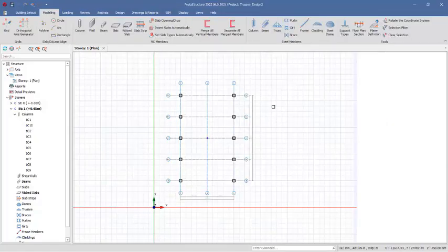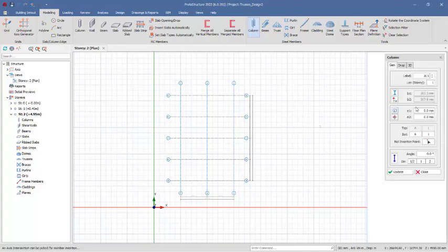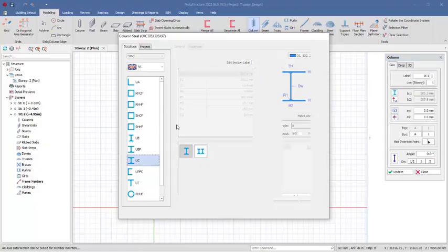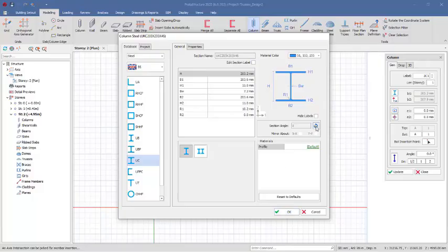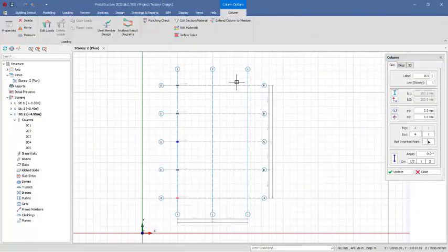Alright, after which we can now navigate to story 2. At story 2, we're placing our stanchions. So click on the steel columns. We change these sections so we can get smaller sections of the universal columns. So select there. Okay, so we are considering British. This is 303 by 303. It's quite big, so let's go by 203 by 203 by 46. Because it's a small structure, we add that up. We are going to be rotating in this direction. Click on OK. So we have it placed on these provisions, just like this, and the same thing here.